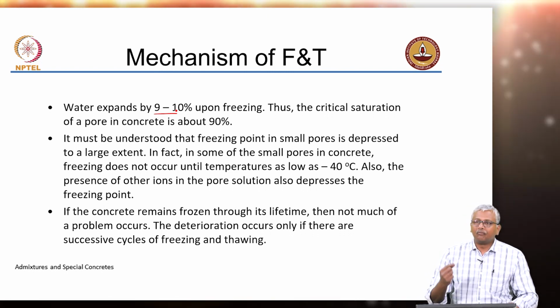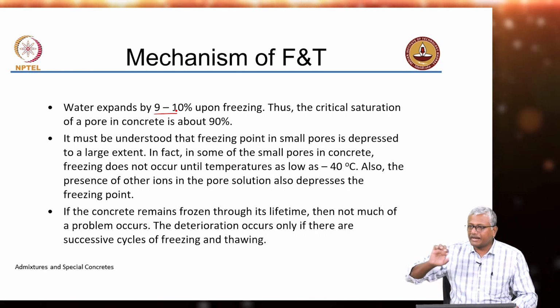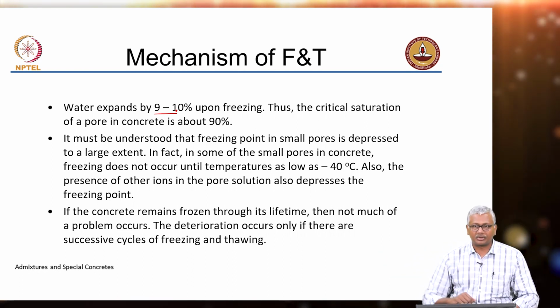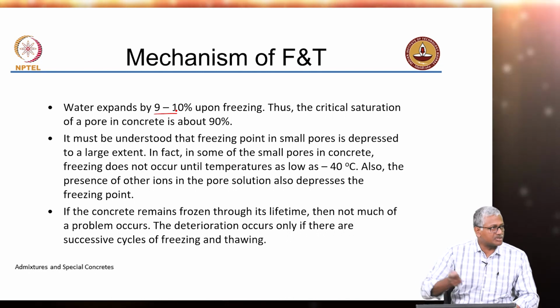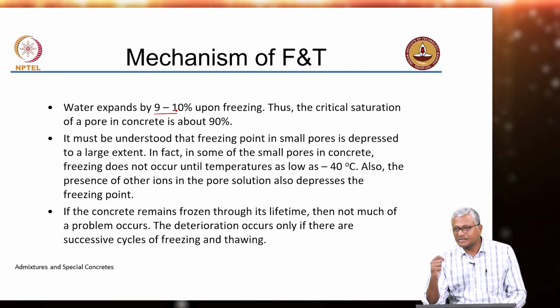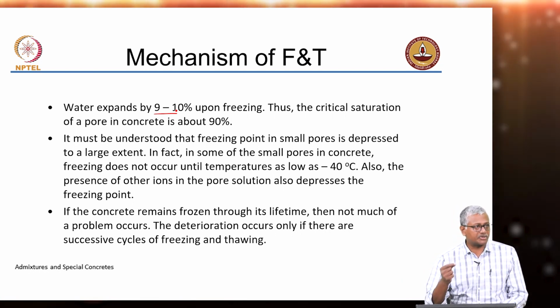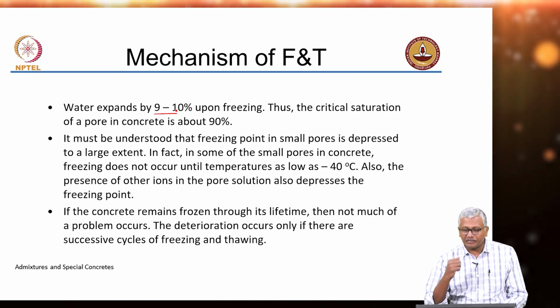When water inside a pore starts freezing, it expands and pushes out the balance of the water. And when it starts pushing this water out, it has to flow through the very small porosity of the concrete. And this flow of water through small pores leads to hydraulic pressure. Okay. So, that is the primary idea.